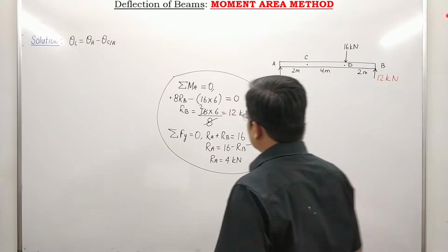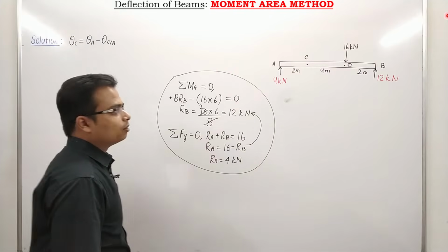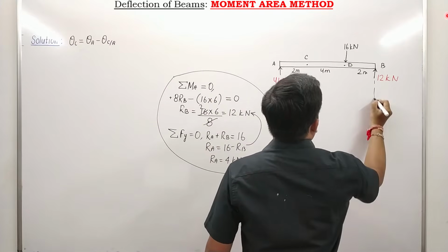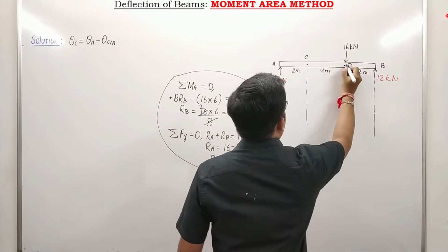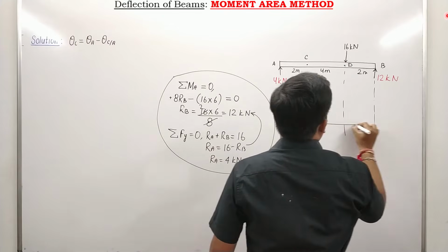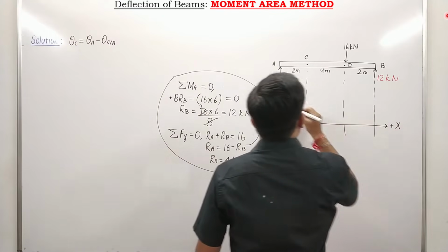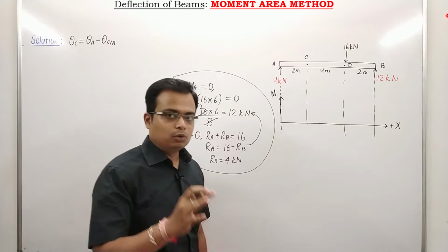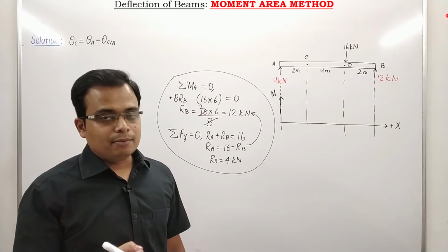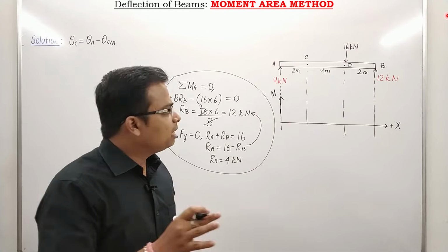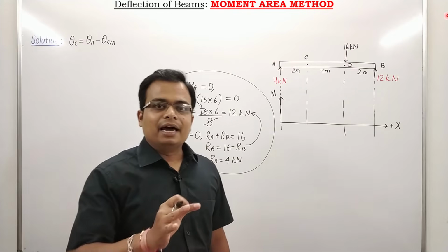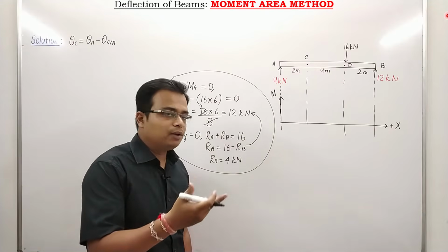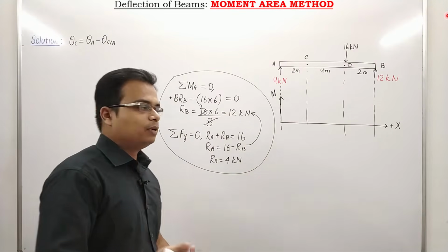Okay, we need to also learn how to make the bending moment diagrams. Just take a look. This is going to be brilliant. Okay, let me make the reference lines. Here we go. This over here is the positive x, and this over here, let's say, represents the bending moment diagram. Although we are very sure that we need to make the M over EI diagram and not the M diagram. You simply have to divide all the bending moment values by EI to draw the corresponding M over EI diagram. That's very simple. Once you have the moment values at different points, obviously everything else falls in place.